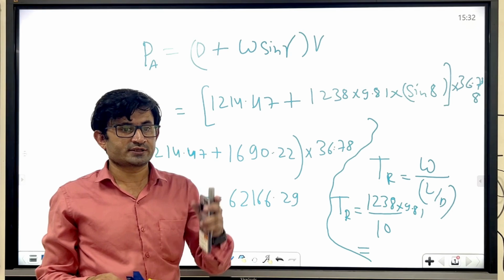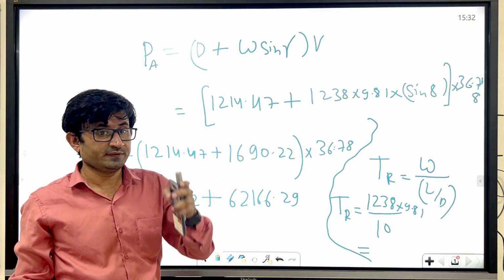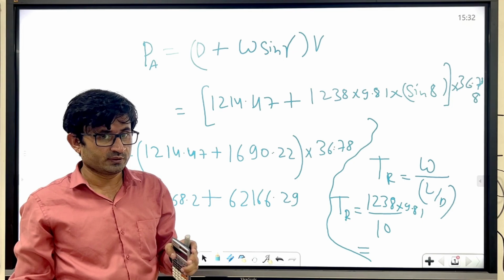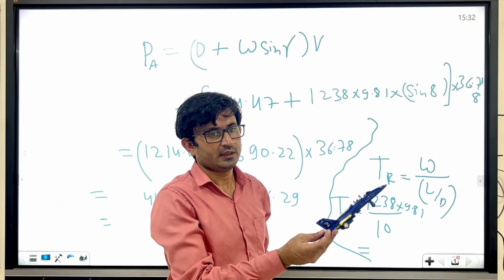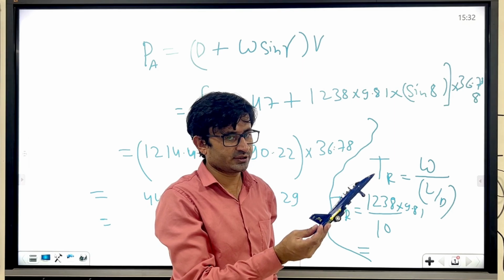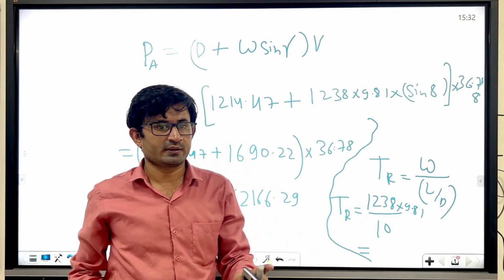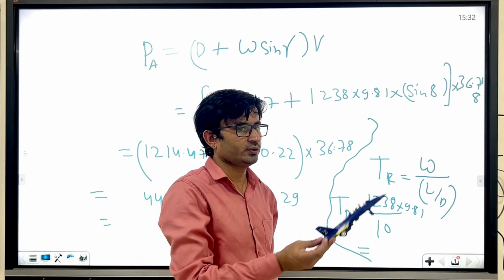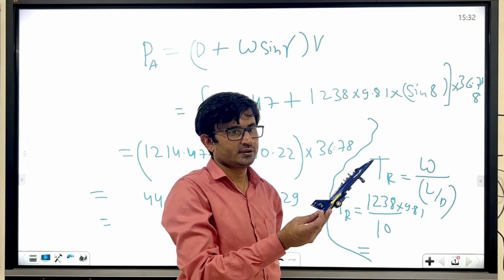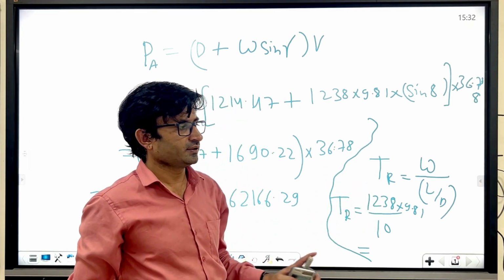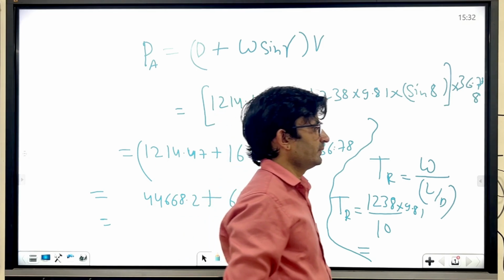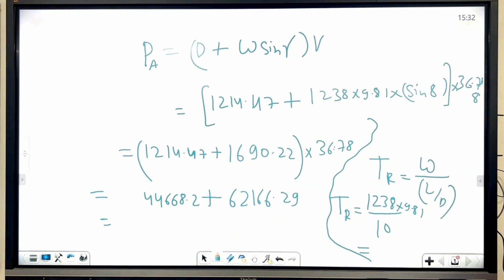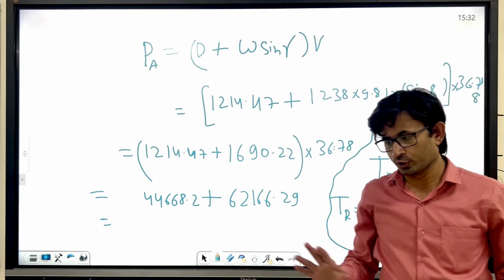So now you have excess power, 100 minus 50, 50 watt. From that excess power you will try to climb, and you will reach the altitude where power available will be equal to the power required. As long as you are increasing the altitude, your power required is increasing. If it reaches the power available, then you will stop attaining new altitude. That means your climb rate will be 0.